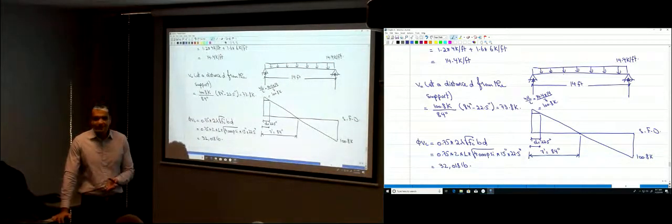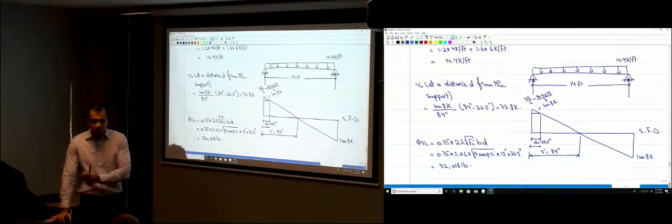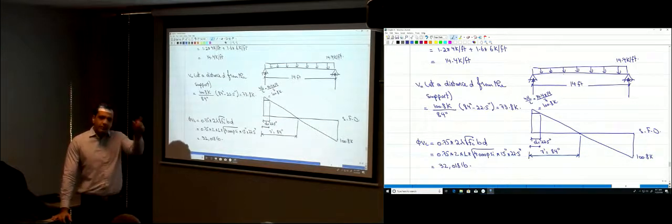Does this make sense or not? So at what point would 9 inches spacing be enough? Find out from the equation, I guess. Yeah, you find out how much shear force can be resisted if you have 9 inches of spacing and see where the shear value equals that value. Then at that point you can provide that spacing, the 9 inches spacing of stirrups.